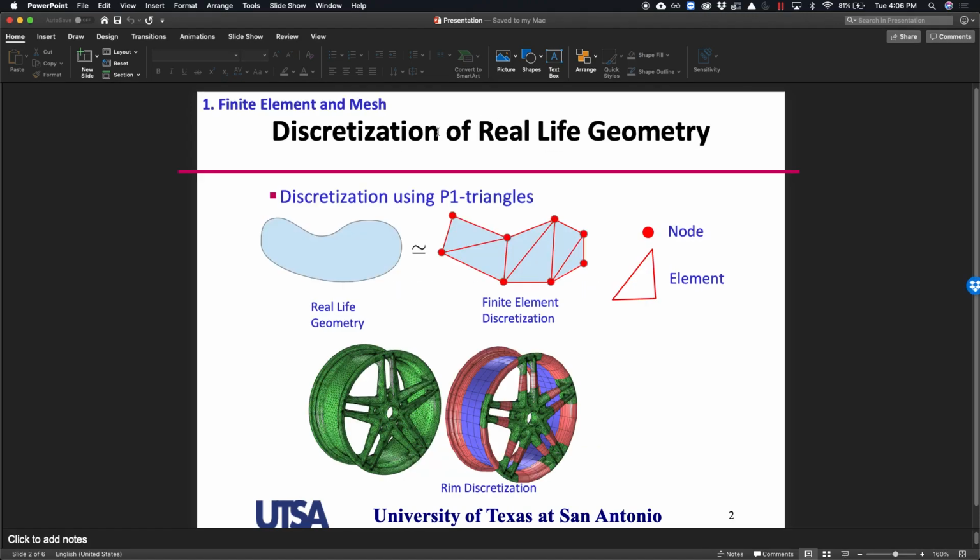Finite element modeling: you take a structure. There are some analytical solutions, so you can go to a handbook and see what the stresses in a pipe or a plate are. But for more complicated structures, you need a computational tool to solve that structure and see what the stress distribution or the displacements inside that structure are. Finite element methods is the most common tool to solve those kinds of problems.